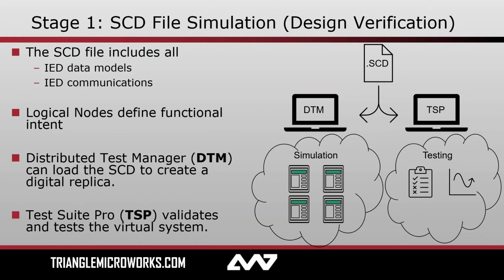I think digital replica might be the more common industry term, but an approximation of our system that is accurate to the degree that signal exchanges are mirrored, everything communication related is mirrored. And then we can validate that the signal exchanges that we are expecting to occur in order to meet our protection, automation, control goals are in fact happening, and that our system is working as intended.